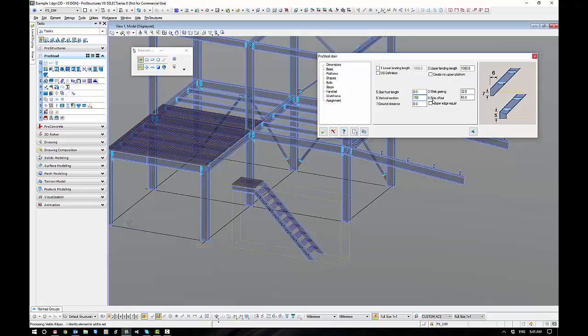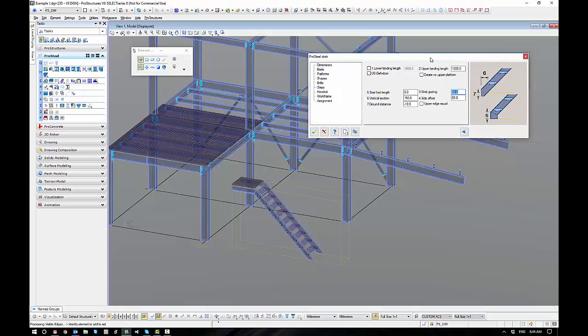So I'm just going to make a couple of changes here. I like to crop the bottom off, or the front edge off my stair, so I'll just knock that back, and you'll see that the stair will update, though it's a little bit hard to make out. Minus 10 means it gives me room to put a 10mm base plate on. Check your grading. I run 32. A lot of people run 25, so just watch that one.